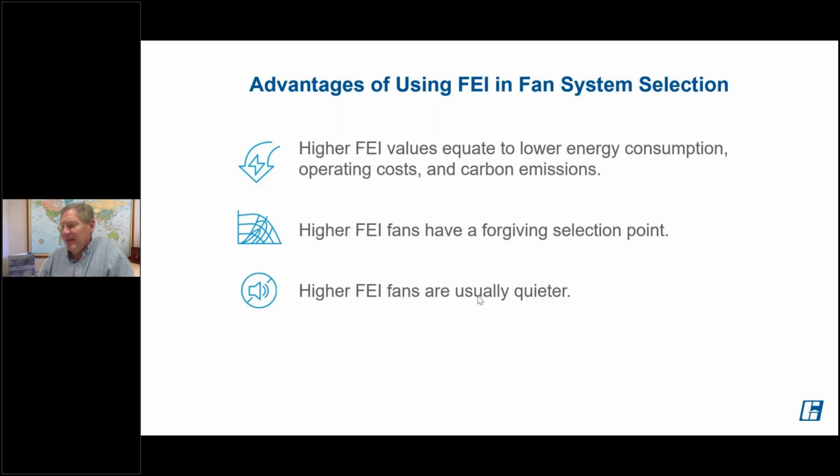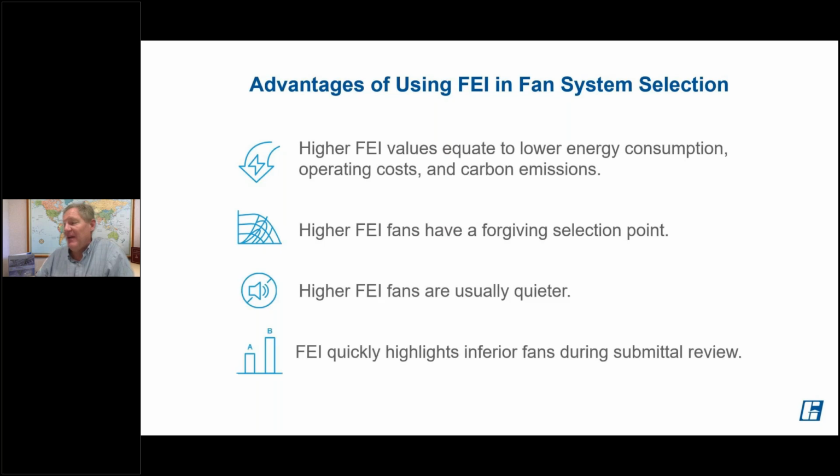And then also, when you have a higher FEI, generally the fan's going to operate a little quieter. And the other cool thing is when you're doing your submittal reviews, and we'll talk about adding FEI to your fan schedule on your submittals, it's going to allow you to quickly highlight potentially inferior fans, or fans that are being bid or supplied that are not necessarily apples-to-apples comparisons. So we'll give you some guidance on that as well.